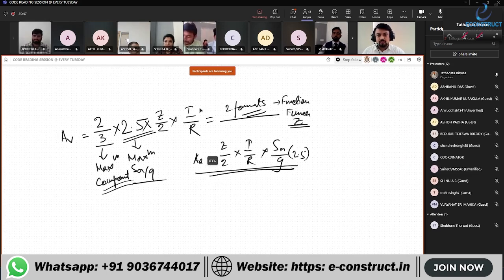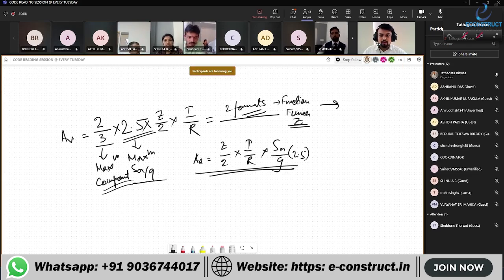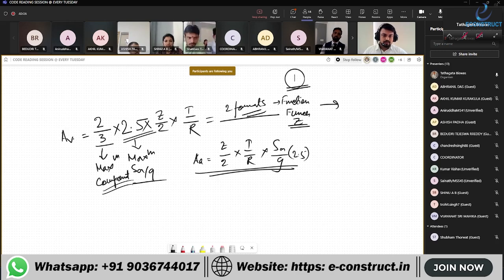Right? Okay. So this is the formula for AV. There are two ways to put this formula in the software. Number one, you put this entire thing in a function, under the function which is fz, that you need to create. This function has nothing to do with the previous one you created. You can name it IS1893 and create a separate function, and there you put this entire thing, calculating it, and in each time period you need to put that.